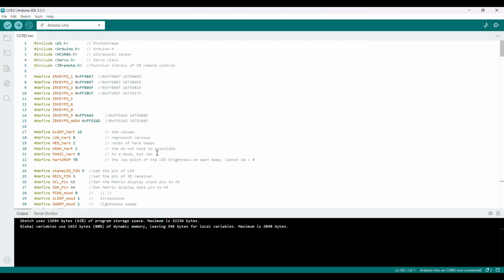So that will be coming in a new version of how the Protothreads are set up, and a new version of the state. We have to write a new servo handling routine because the servo class clashes with our LED on pin 9. And then maybe even start doing some testing on the motors. For now, that is all we have so far. But once we've got that servo operational, turning the head or turning the ultrasonic sensor, I'll cook up another video and we'll have a look and see what it looks like.